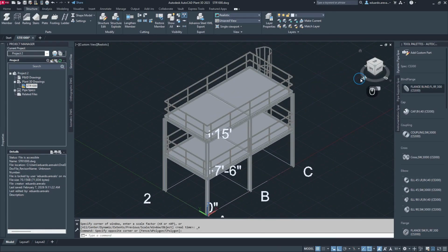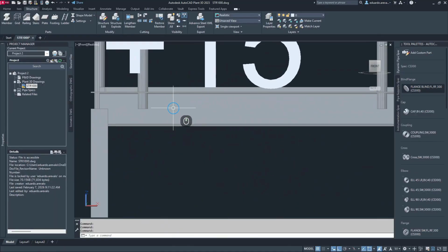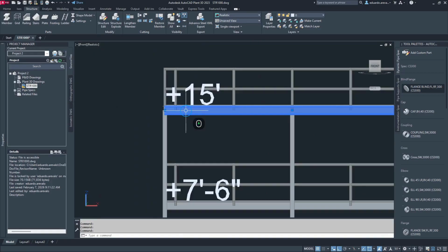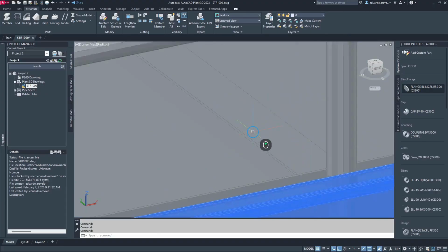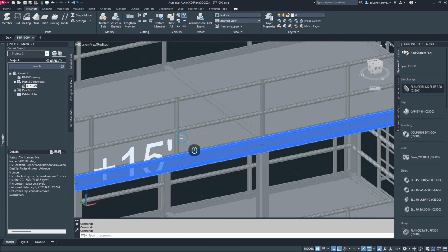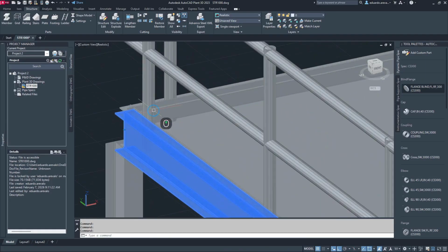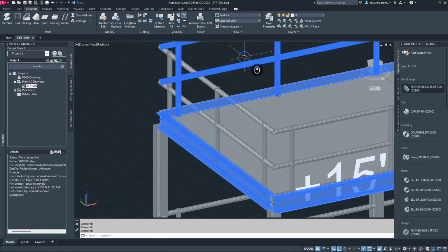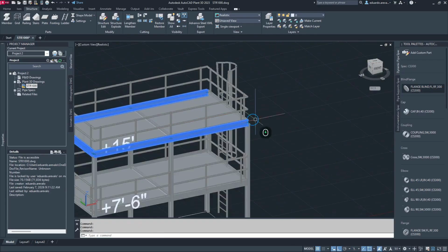You are free to play with the options. You'll see how you become more comfortable the more you use it. Say for example, this level is actually, as you can see, sticking out of the plate. So I'm going to lower the whole level here by selecting the members. Just select the rail, so I want the steel frame here.